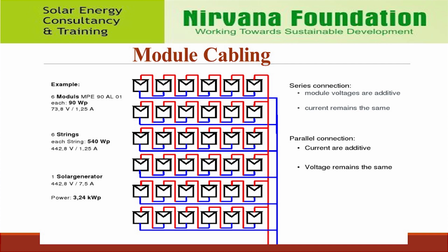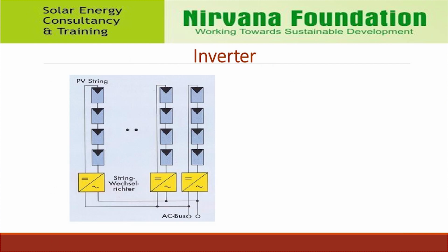Inverter. String inverters. String inverters are a distributed architecture for solar plants. They're small, and each unit converts a much smaller amount of power than a central inverter. Since string inverters are converting less power for fewer panels, if one string fails, the whole array's energy is not lost, just the power from that string.